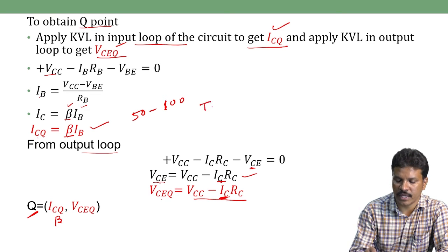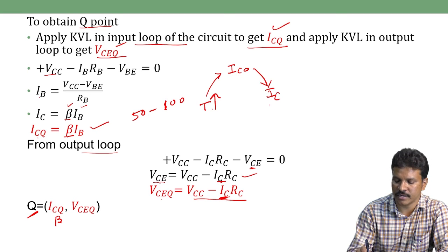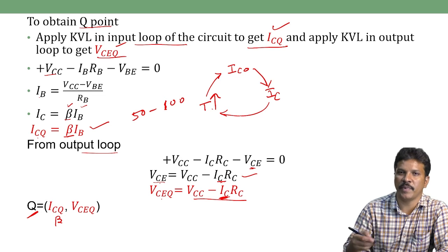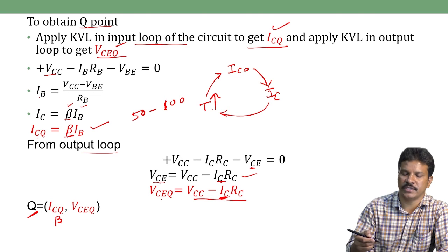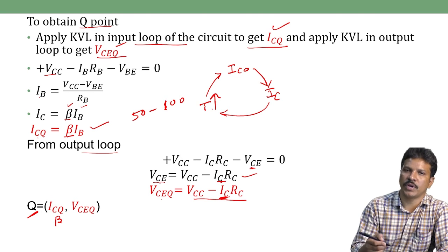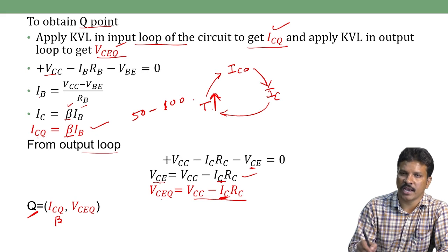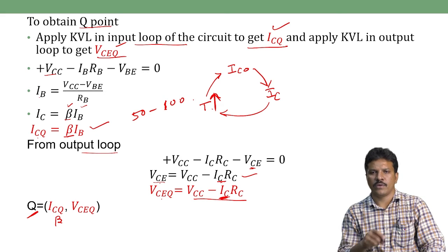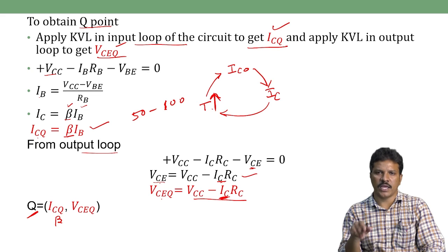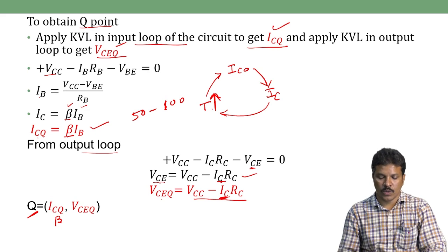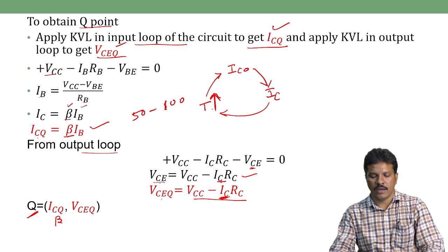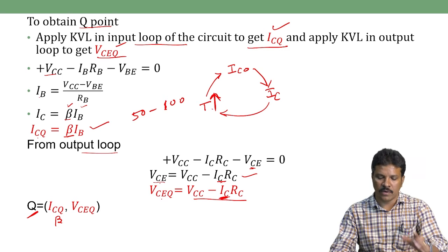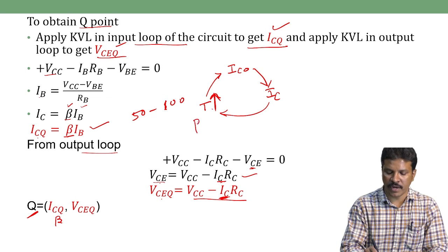When temperature increases, ICO increases, reverse saturation current increases. When ICO increases, collector current increases. Collector current increases, which will make more heat generated in the transistor, so that it will lead to temperature increasing again. This cycle repeats and keeps going on just like a circle, so that it will be unstable. The circuit is unstable.